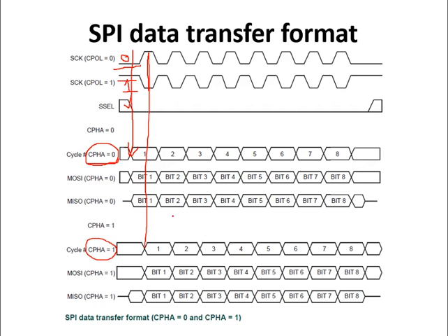When it is 0, the clock edge is from 0 to 1. If CPOL is equal to 0, at that point, after that, the data can be modified here. Here the data is captured. You can see that when you can modify the data is decided depending upon whether CPHA is equal to 0 or CPHA is equal to high, the clock phase.